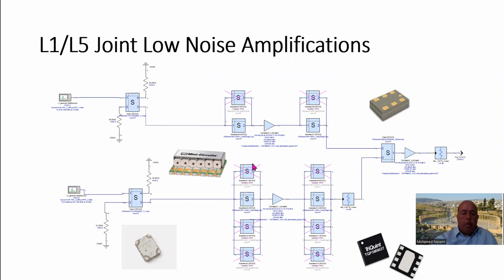And the L2 in here, I have as an example many of these filters stacked up. But right now the cross in here shows that it's not simulated, meaning only this one and this one are simulated. These are assumed to be not in the design. And the reason I have them is because I switch them back and forth to configure the LNA for various GNSS services like GPS, GLONASS, Baidu, and the Galileo, okay?